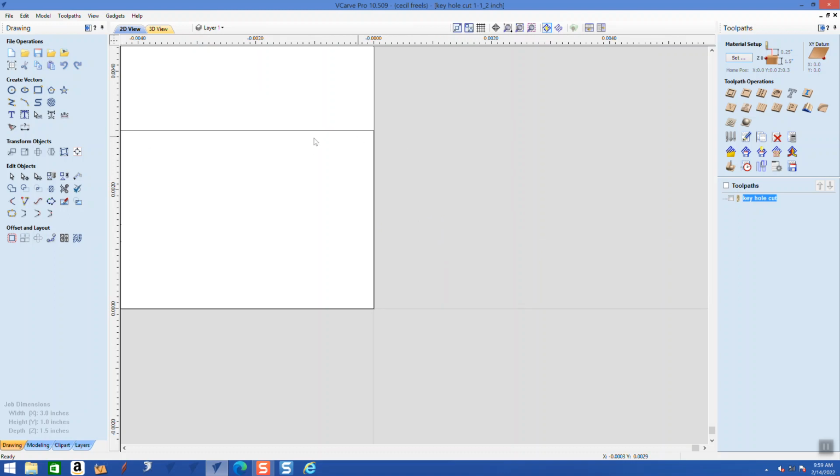That's 0.003. I'm going to go to my node editing tool, and I'm going to do two things. I'll select this object and make that point my start point, and I do that by doing a right click and coming down to make point start. And I'm also going to take this point and drag it down here almost on top of this one, right there. See it?